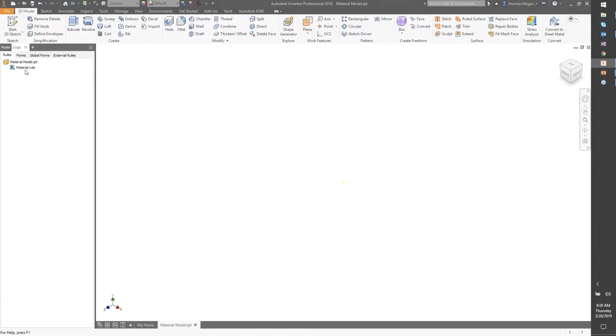So this is a rule that you would incorporate into your template. As your users start developing components associated to an assembly, perhaps, we're avoiding using the generic material type. And how it works is if I run this rule, it's just going to do a quick check. It's going to say, hey, the generic is not a valid material.